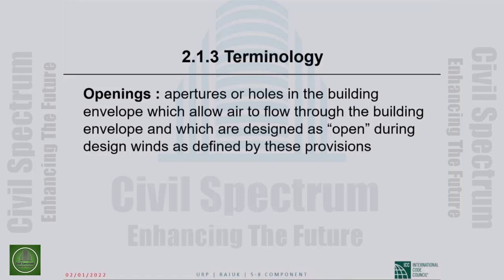And in ASCE 7, or I don't know where, but the way it is practiced, I can assure you, is an operable window, windows we always assume open, openings. There is no question in design. The doors we also take as openings unless there is a crew in place, instructions in place, making sure that the door will in fact be closed at the approach of a storm.